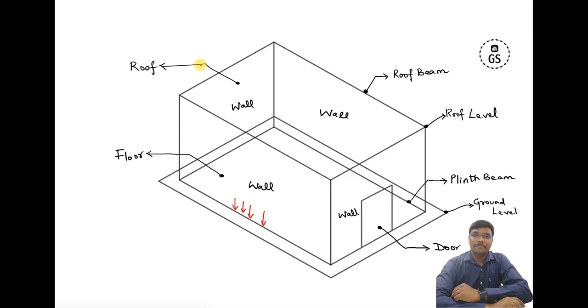If you are talking about the slab, we have again two concepts, one-way slabs and two-way slabs. Basically we take two-way slab designs for load distribution. These loads will be distributed to the particular beams. This one over here, and all four sides of the beam, the loads will be distributed from the roof slab. Similarly from the beams, this load will be distributed to a column. Then from column again it will be distributed to the beams as well as to your foundation part.